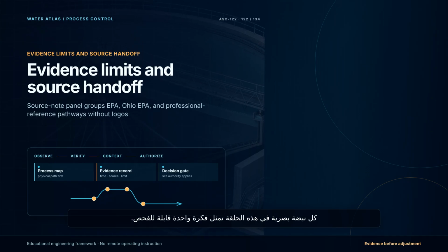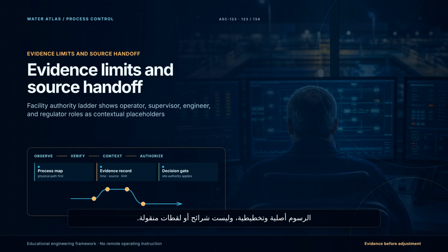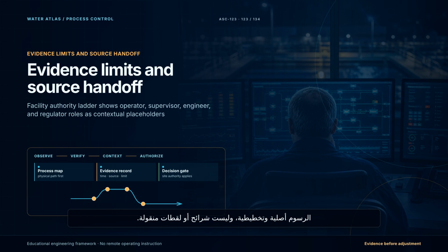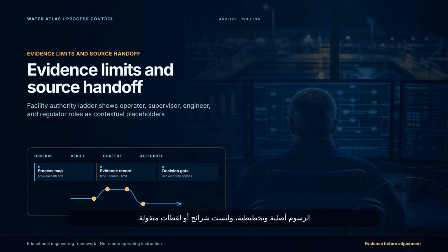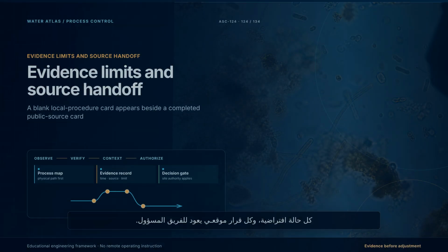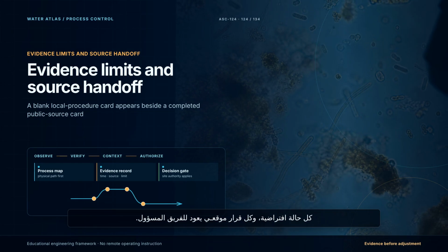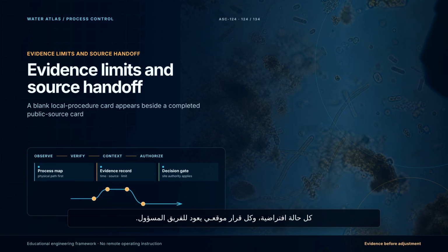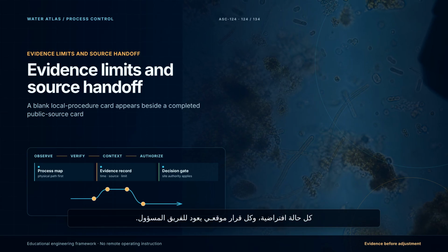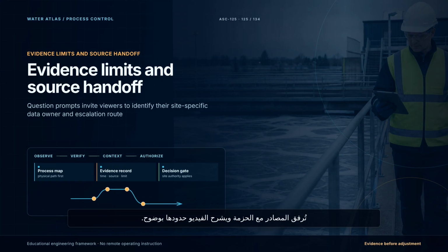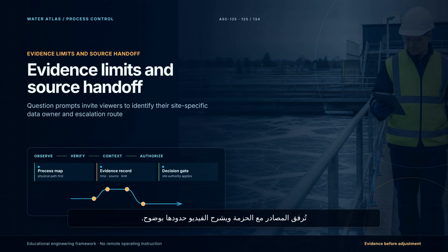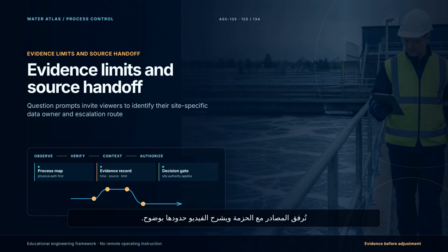A strong review meeting is not a presentation of certainty. It is a structured conversation. One person may summarize the influent and weather context. Another may report aeration basin observations and equipment status. Laboratory staff may explain samples, methods, and trend confidence. Clarifier observations and solids handling information can then be reviewed alongside treatment results. The group should identify what is known, what is uncertain, and which question matters most next.